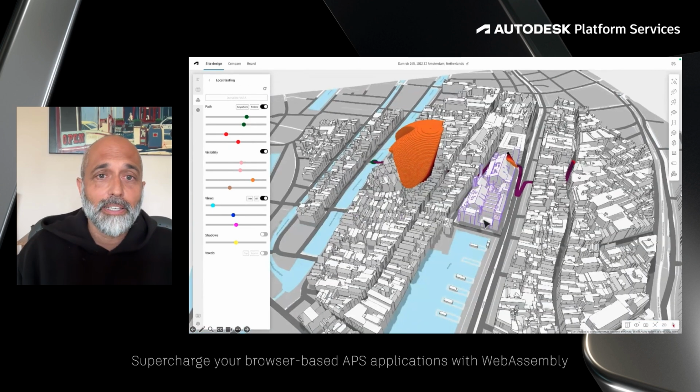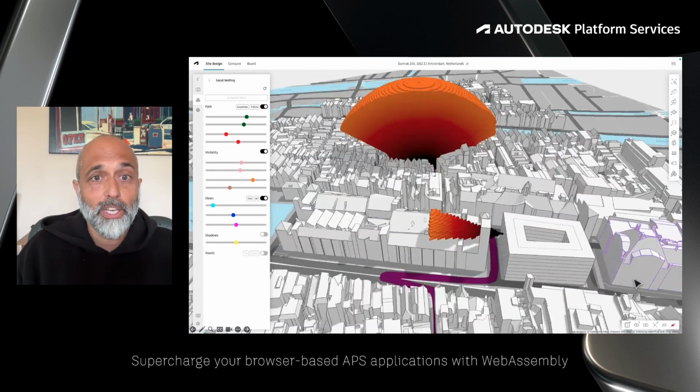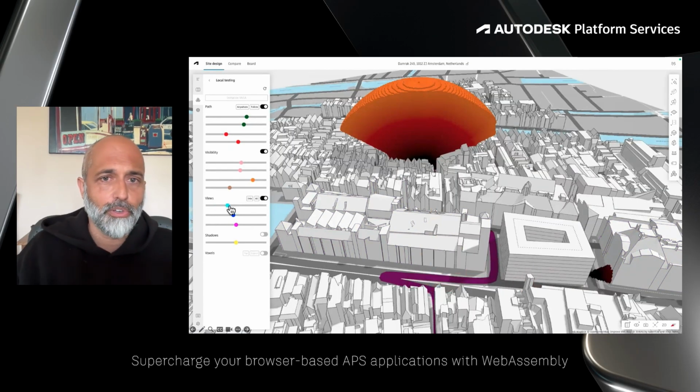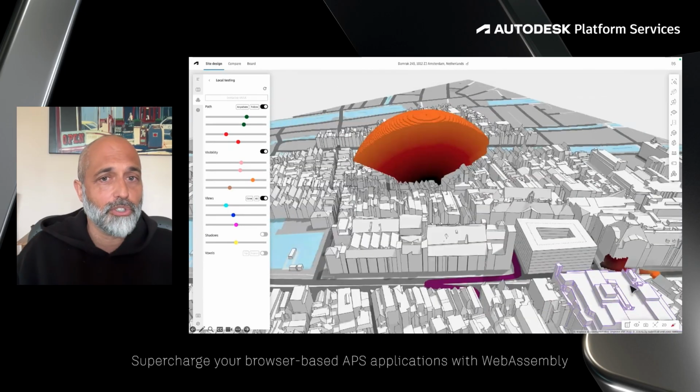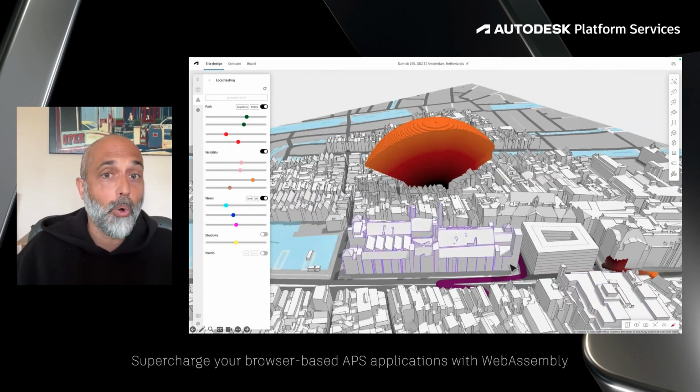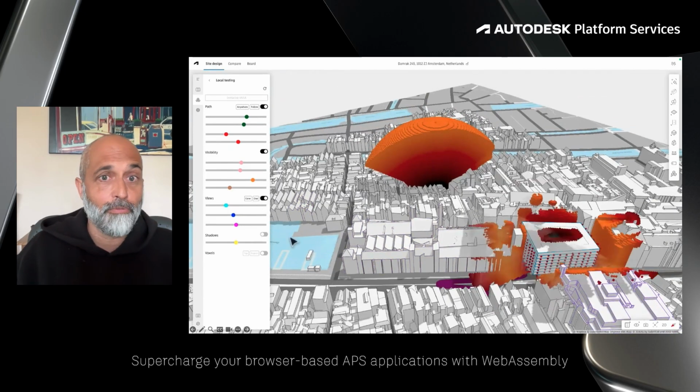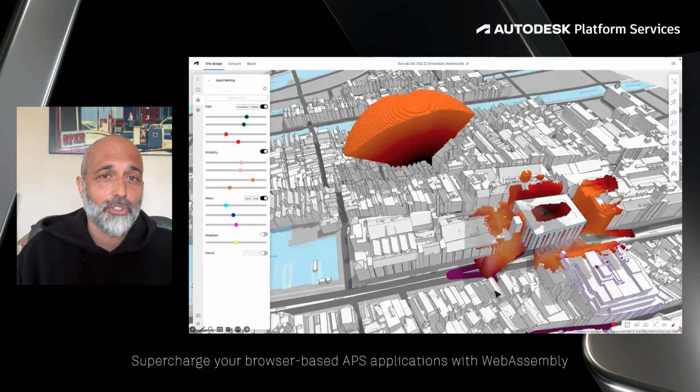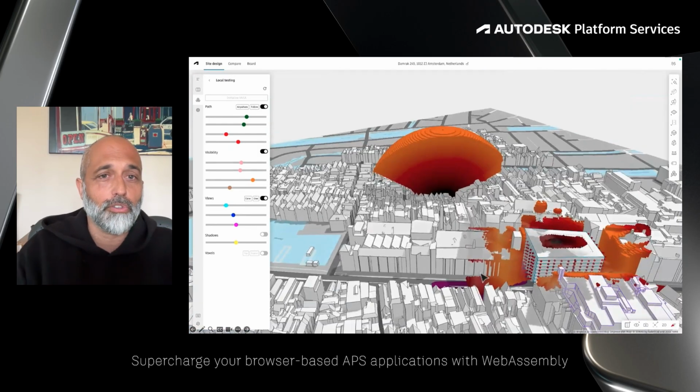The next thing we're doing is checking visibility from different windows of a building that we've modeled inside this environment. So you've got a visibility cone. You can modify the radius and the length of the cone. You can also specify whether you want to show the cone itself or just the areas where it intersects with the geometry. And then we can just say, show me all of the visibility cones from every window of the building, which shows overlays voxels on all the buildings around it from there, which is kind of interesting.